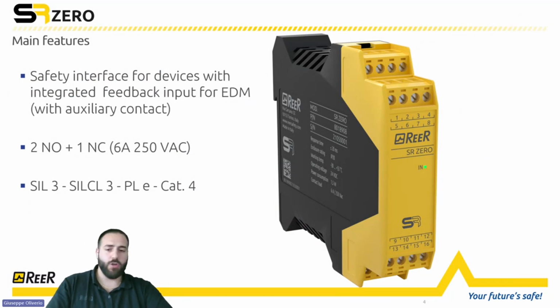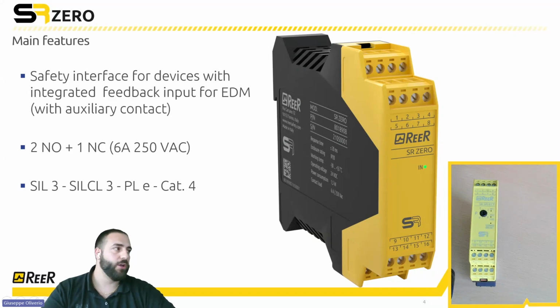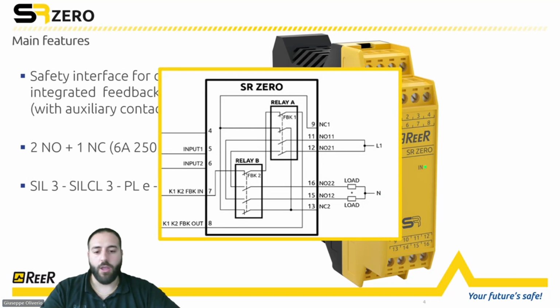interface. So again, the SR0 is used with devices with OSSD output with integrated functions like the EDM controller, reset, manual reset on it. What you can also do is to directly connect the signal to the SR0. Like in this case, you can connect the feedback input.